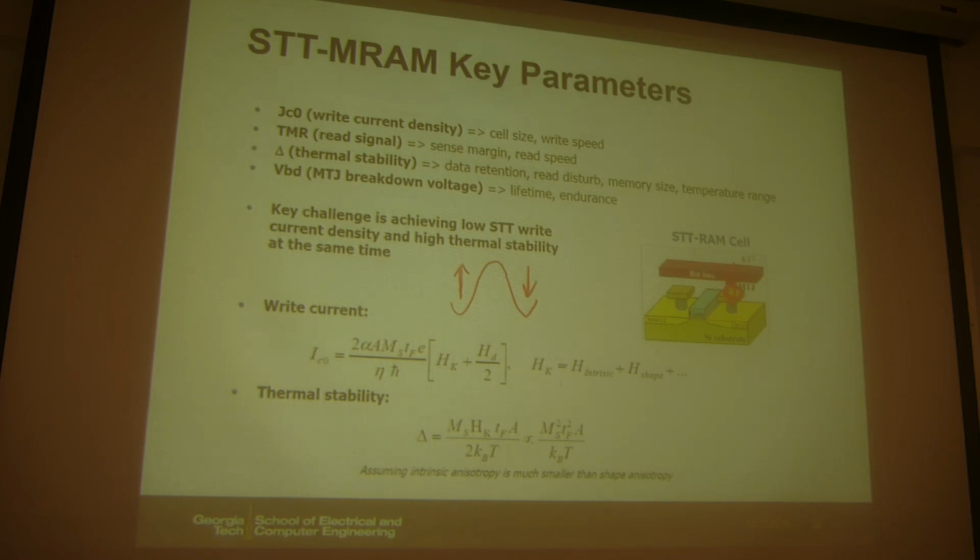If you pass too large a current, or if you have this STT-MRAM chip in a very strong external magnetic field environment, then of course the data will be lost. That's actually a concern for the STT-MRAM. If you use that chip close to some external magnetic field, in medical environments, then it will not work. Okay. So the pin layer will not pin.